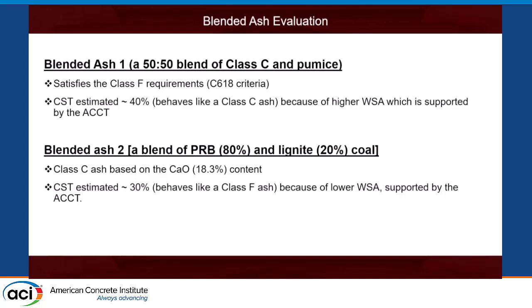So class C, class F terminology really has no relevance. The relevance is how much it is modifying the pore solution alkalinity of concrete. That's fundamental. You don't have to go by class C or class F or anything. Any alternative material can be tested with this approach.